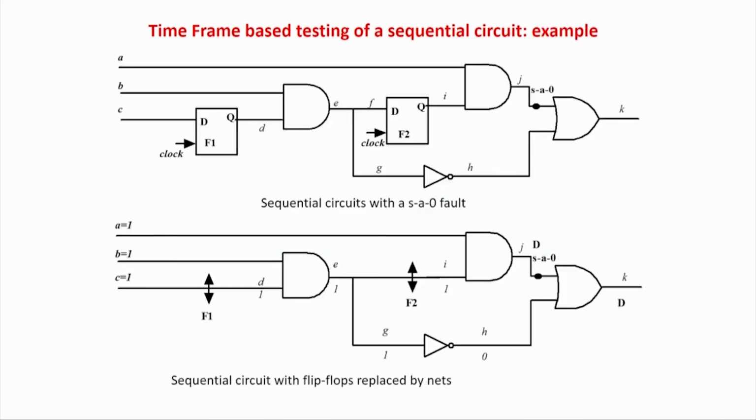If, for example, the circuit has some flip flops with 20,000, 30,000, 40,000 levels, then what will you do? You have to keep on pumping the values and it will take some 10,000 or 20,000 time units, because some flip flop is at the level of 10,000. That means 10,000 primary patterns have to be applied at 10,000 different clock pulses. First it will set flip flop level 1, level 2, level 3 and keep on doing it. So, a lot of time will be required to pump in the values.